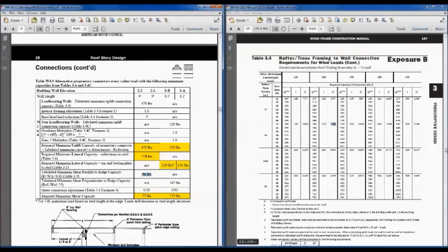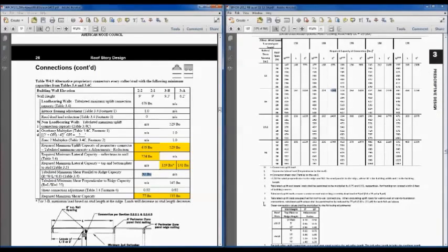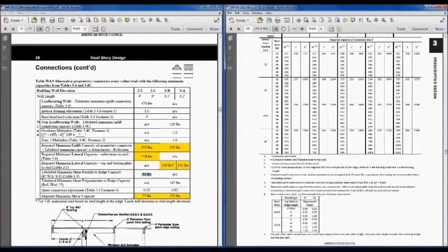And then there is a shear connection adjustment here in footnote 4 that kicks in above 6 and 12, and at that top plate to ridge height of 9 feet, which we have, and so that ends up being a 0.92 factor. So again, looking at all these factors, you can come up with your required shear connection. But it's a lot easier just to pull them out of the table where that work's already been done. If you want to run through the calcs, it's here.